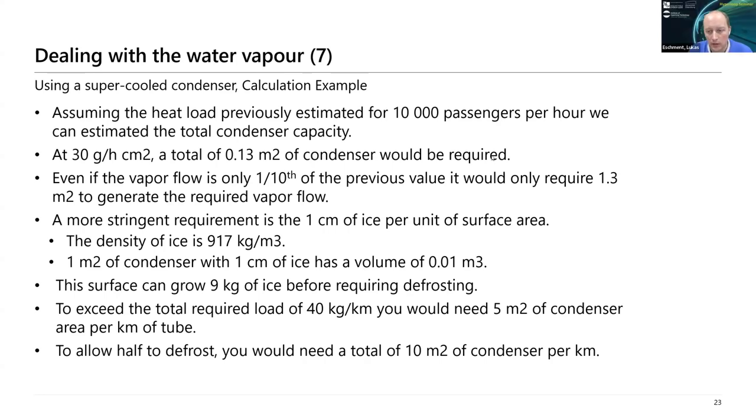Yeah, and then I think Nick also asked about very much lower pressures. So if you go down to not only 2 millibar or 0.1, but a lot lower, I think that requires other pump technology. So you would also increase your energy. Turbomolecular pumps, I think, for these kinds of pressures. So that makes for unfeasible amounts of power. Depending on it, the pump technology needs a lot more power, yeah. Already a bit lower than the 1 millibar. Yeah, but not too much, as we would say for that one.